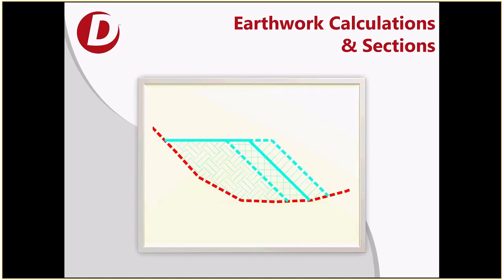And again, just like with the ground compaction, you need to be proactive and require that your geotech consultant give you an estimate of shrink swell factors in his geotech report. And they like doing that even less than they like doing ground compaction, because shrink swell is kind of black magic and a lot of potential for error. But again, they're the experts. Put their feet to the fire and make sure you get that number from them if you have a significant quantity of embankment and you think that the shrink swell might be significant.